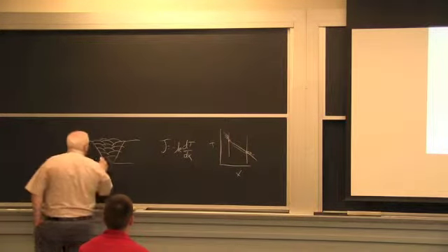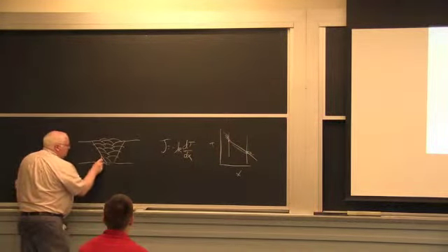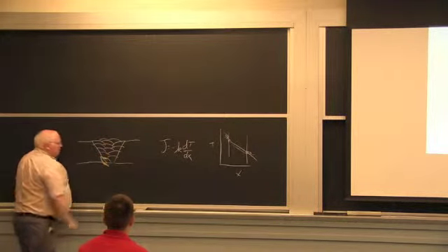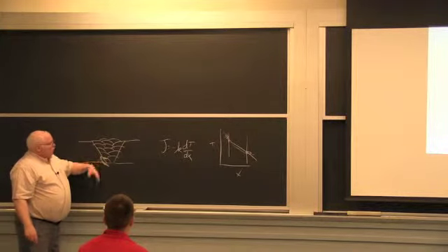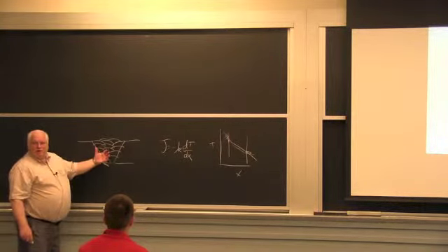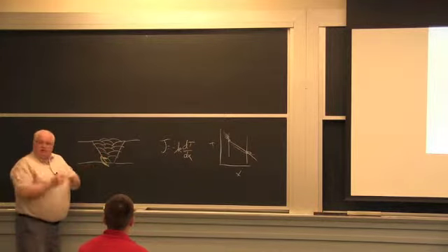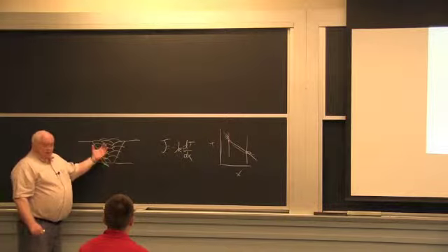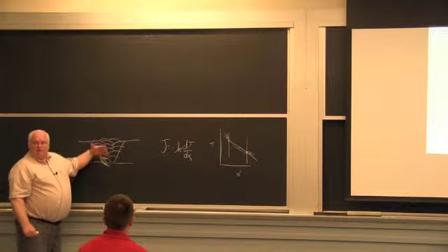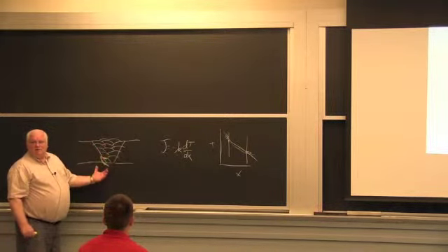So in many of your heat-treated steels, you would like the heat affected zone around this weld to temper the bead underneath. Well, if the heat affected zone is too narrow, I don't temper the full bead. So what size pass can I put in? A lot of times you're limited in the size of pass in some of these pressure vessel steels because I want to have a heat affected zone that will encompass the bead underneath.